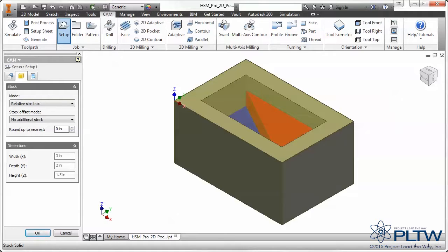the facing operation. The previous 2D pocket strategy presentation showed the bottom surface or bottom edge of the pocket as being selected for the geometry selection. Using this approach requires that the bottom of one pocket be selected and then the bottom of the other pocket is selected next. This is not efficient because the first operation would remove the material directly above the bottom of the first pocket, then remove material above the bottom of the second pocket.